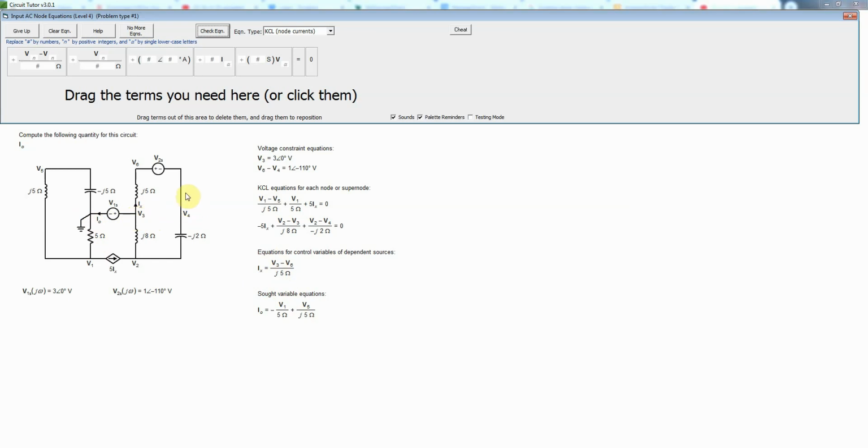Instead, we'll go to node 4 and write a KCL equation there, but again, we have a voltage source connected to it. So in that case, we don't know the current through the V2S source, but we can now form a supernode consisting of nodes 4 and 6. So we're going to draw a KCL surface around those two nodes, including the voltage source, and then we won't need to know the current through that voltage source because it's going to be internal to the supernode. So it's not going to be a current that exits that closed surface, which we call a supernode. So we have one current exiting here, which will require that type of term, and then another one exiting here, which requires another term like that, and that's going to be equal to 0.